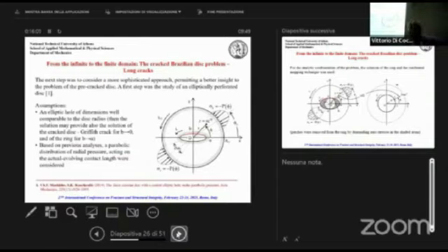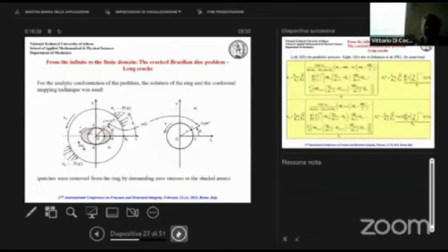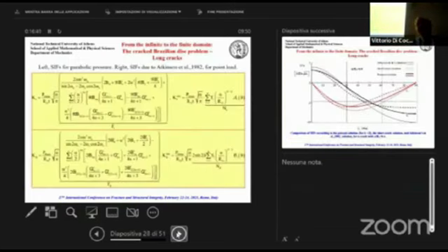And what is left now is to consider long cracks. Adopting the ISRM standard we do not have short cracks, especially the CCNBD, the chevron cracked notched disc. The length of the crack is not very short. Obviously, this problem cannot be solved assuming a mathematical crack, so we consider a solution with an elliptical discontinuity, and then using the minor semi-axis going to zero, we can get close to a crack. Again, the mathematical solution was not very easy. However, the final result is quite encouraging.